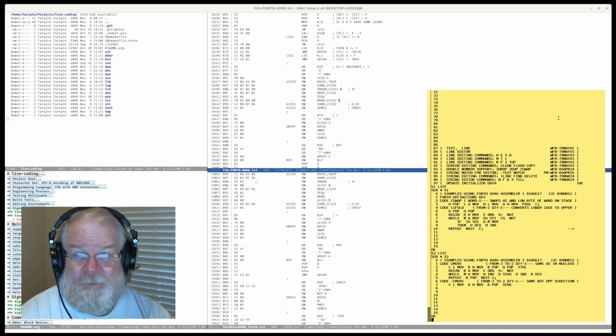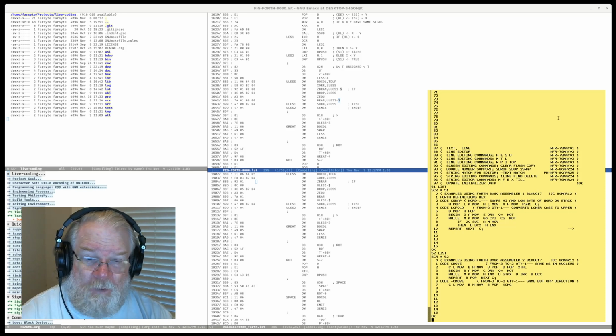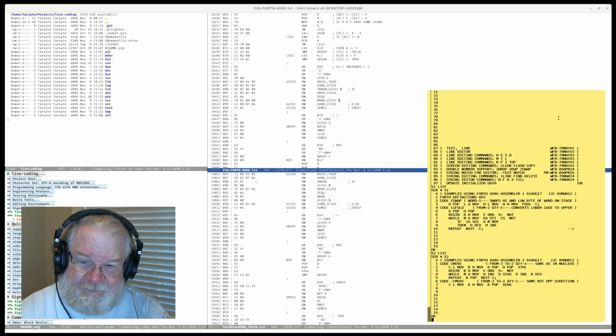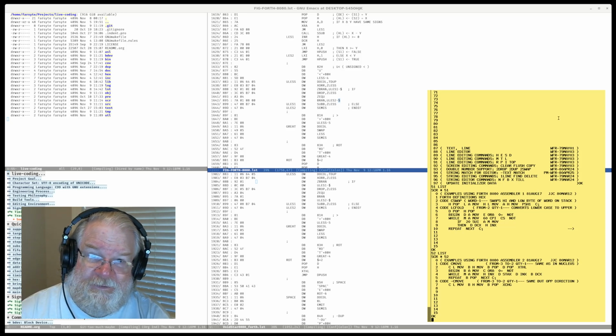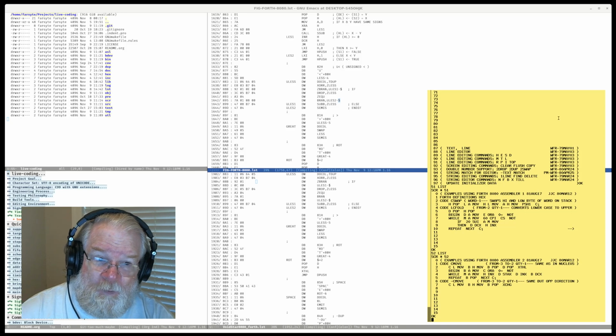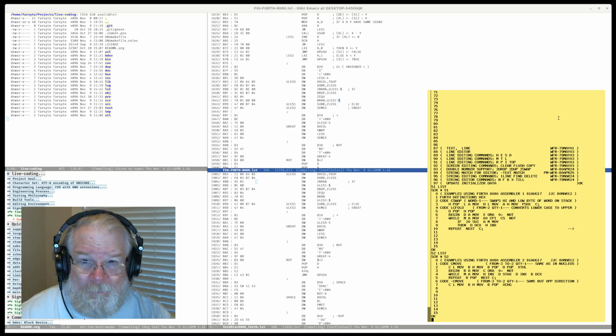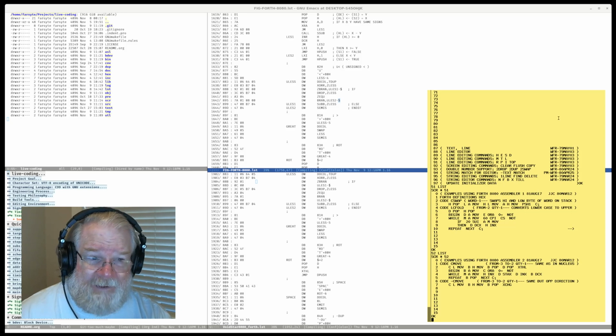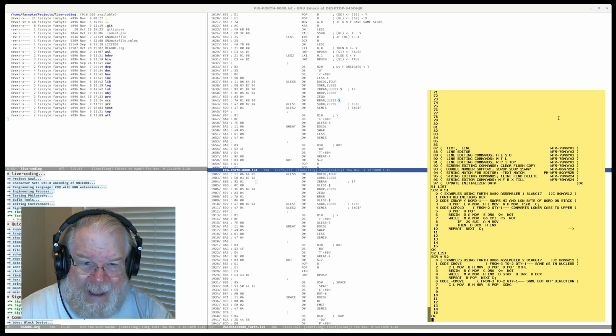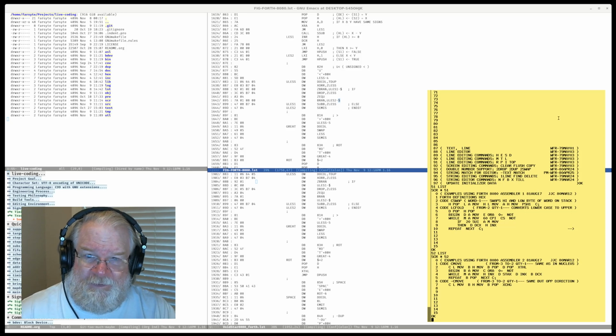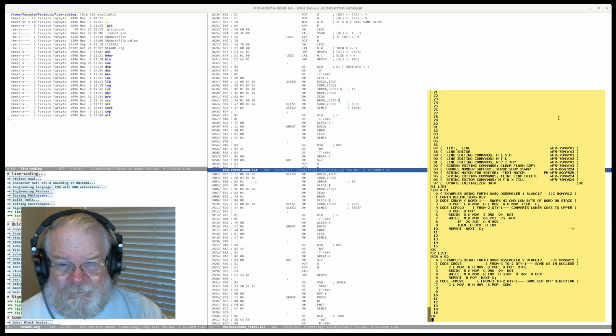This was for a commercial project, which wanted to do some things to obscure what was on the disk. We worked out how to set it up so that as you read the tracks, you'd read the first quarter of the track, and then step by a quarter of a track. Second quarter of the track, and step by a quarter. So if you tried to read it normally, most of the data wouldn't be well under the head, and in some cases, your head would be halfway in between where the data is actually recorded on the media. Very, very weird stuff.